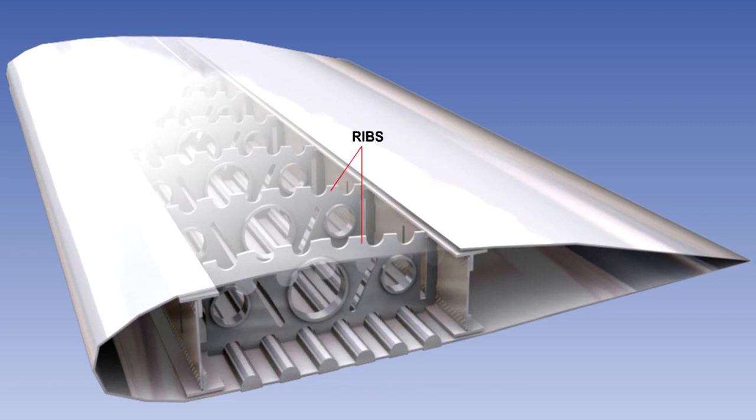Ribs maintain the aerofoil shape of the wing, support the spars, stringers, and skin against buckling, and pass concentrated loads from the engines, landing gear, and control surfaces into the skin and spars. Ribs often have lightning holes cut into them. As well as reducing the weight of the structure, these holes are usually flanged to help stiffen the rib.